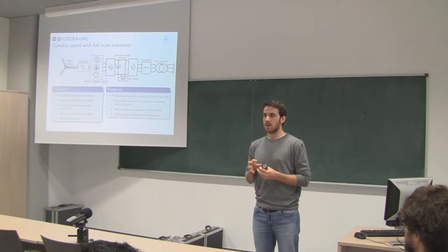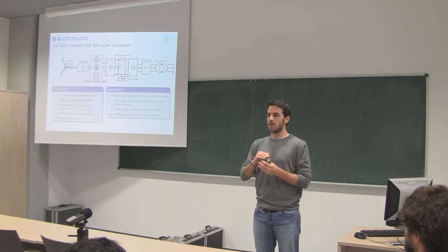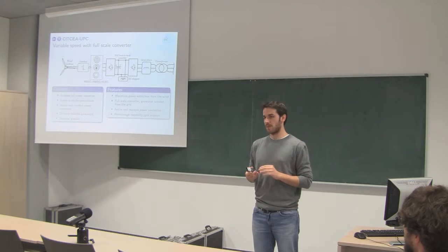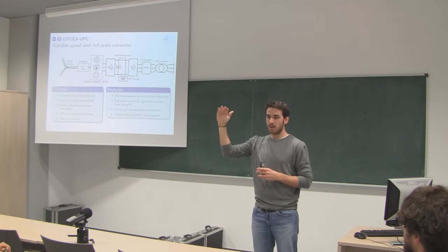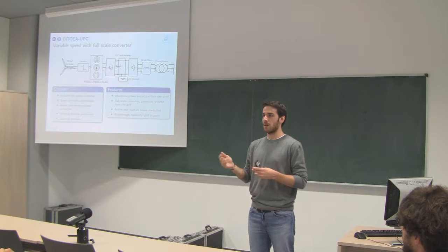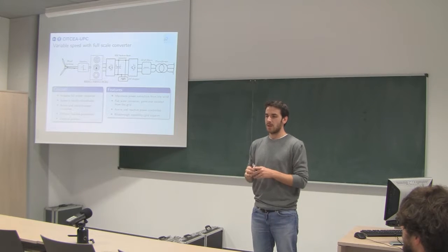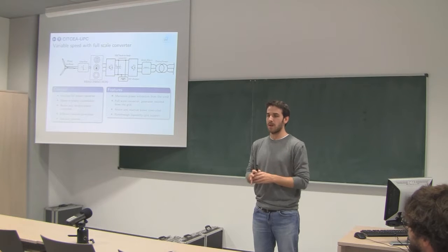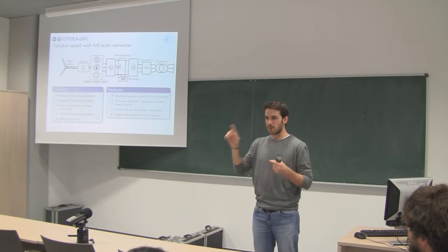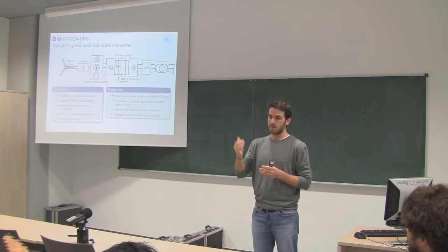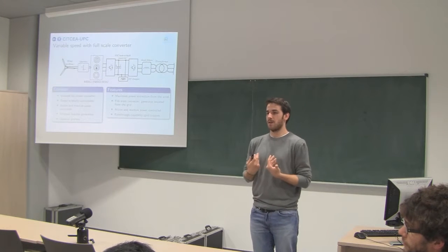This is used when you are operating at the rated speed of the machine, so that your converters are extracting the maximum power that you can, at, I don't know, 13 meters per second, something like that. Imagine that you have an increase of wind power, but you cannot really extract that because you don't have available capability on your system. You cannot extract 8 megawatts because the machine is rated for 6 megawatts. So you will rotate the blades in order to lose some energy extracted from the wind. Typically the blades are at 0 degrees to absorb the maximum power, and as soon as you want to limit the power, you rotate the blades a few degrees in order to lose some. So this power gets wasted. Yeah, not used, because you don't have the capability to extract it.